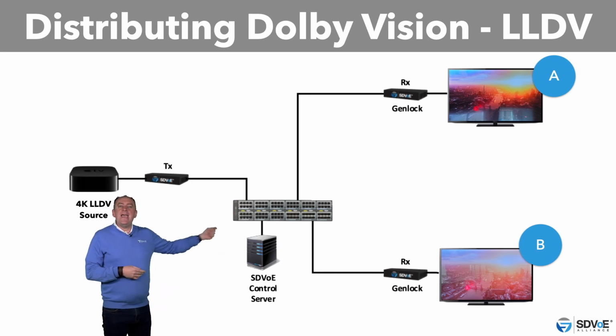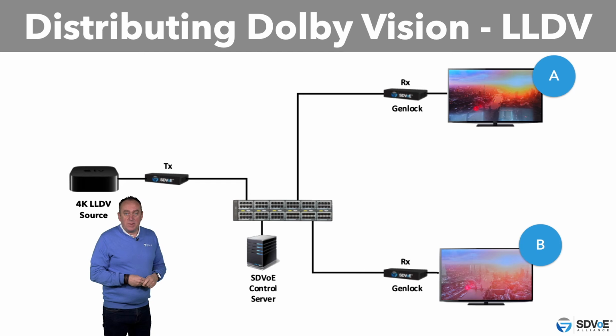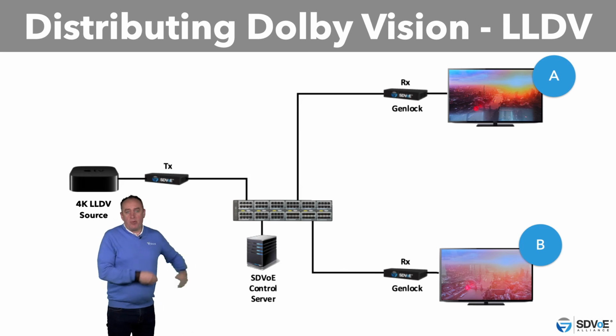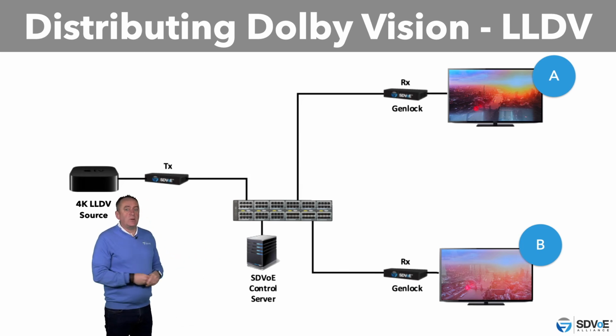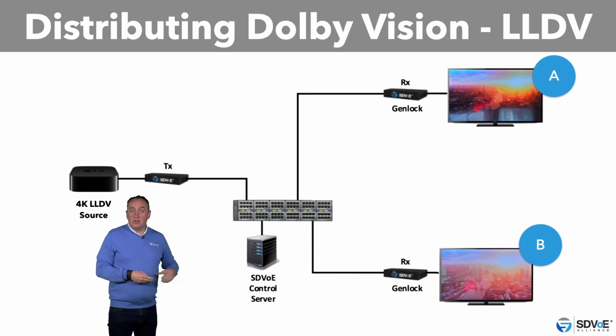If display A is the higher brightness display of the two, then display B may end up with subtly washed out colours. If display B is higher brightness, then both displays will output a picture of similar quality, although display B could have done better if its own EDID was used.